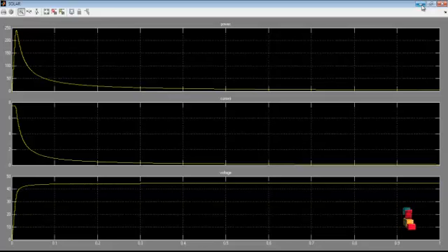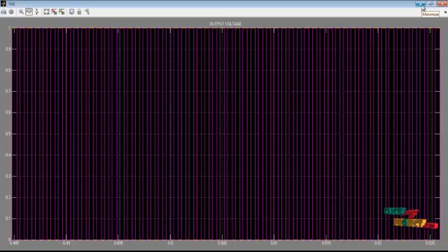So this is the waveform. The first one is the power, and the x-axis is always time in seconds. The second one is current, and the third one is the voltage. And next we see the pulse waveform generated in the PWM generator using the MPPT technique and the controller process. And this is the pulse waveform. This is generated in each division from the duty ratio of the MPPT.